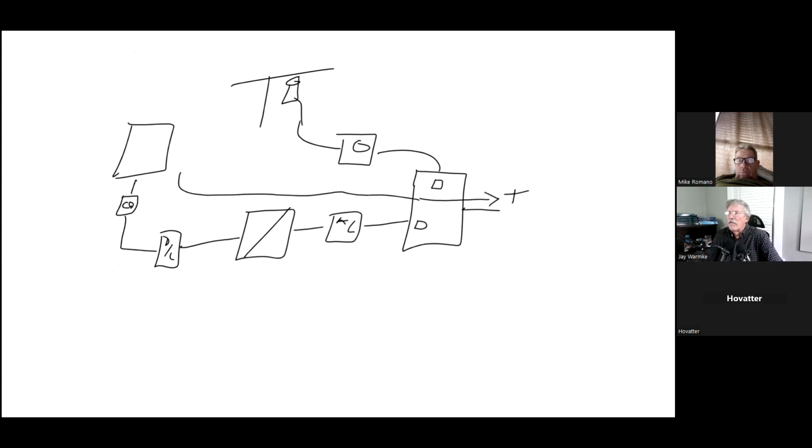All right, what happens if I keep adding loads? Well, it's going to keep drawing power. What happens if I've got more power than what I need? Well, in this case, it's going to service the load, but any extra power is going to feed into the grid, because the grid will act as just another load. And as much power as I'm generating is going to get used up. It's either going to go to my load or it's going to go to the grid, but it's all going to flow through the inverter.